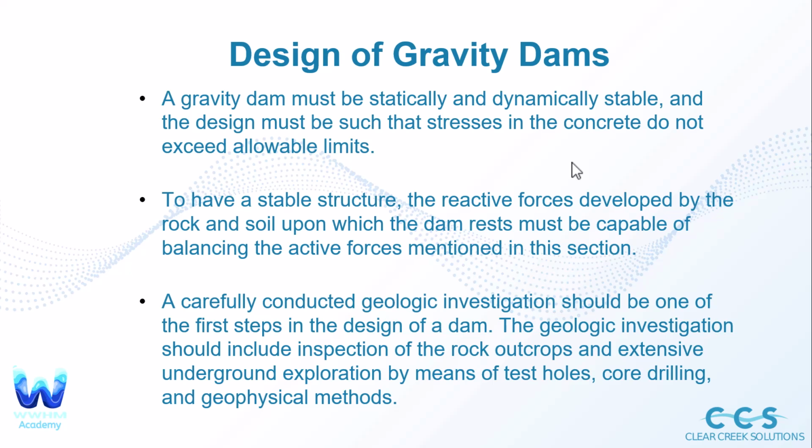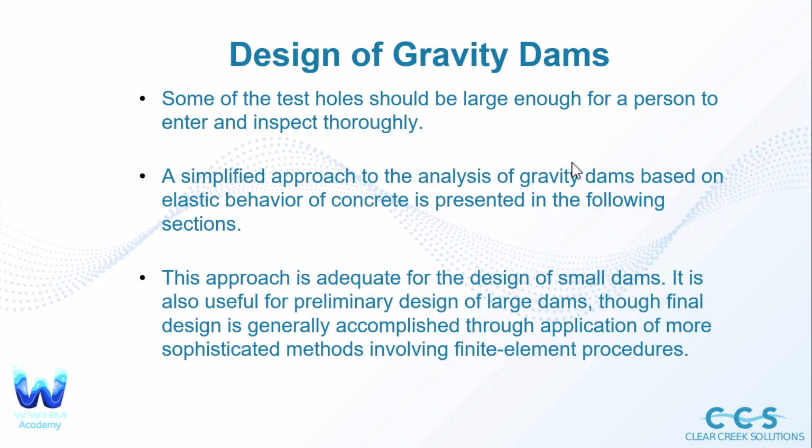So when it comes to actually building the gravity dams, we need a good idea of what is the structural soil beneath the dam itself. What are we dealing with? Because that's going to determine the forces. It's going to determine the unit weight of the soil, what sort of materials we're going to need for the dam, because that's what it's going to be resting on in the end, just like any other structure. So some of the test holes should be large enough for a person to enter and inspect thoroughly.